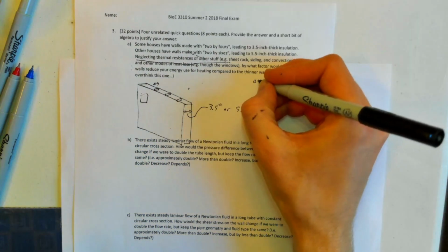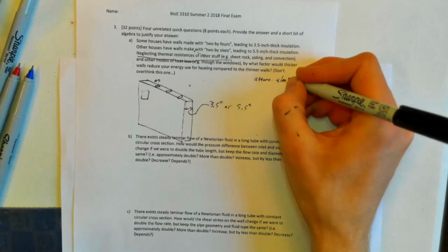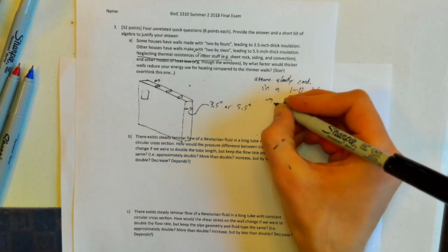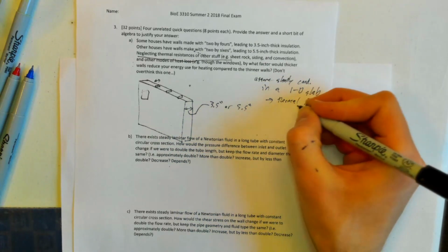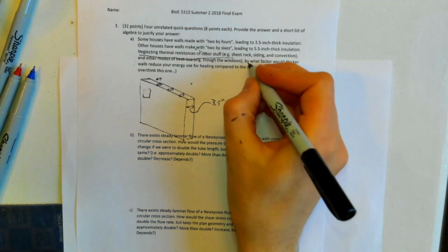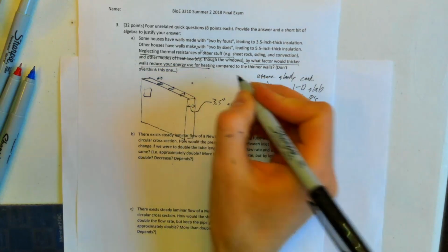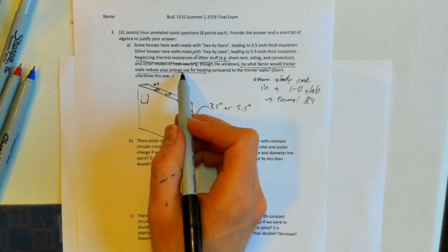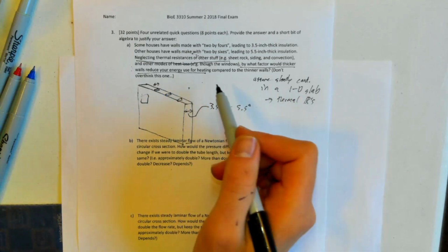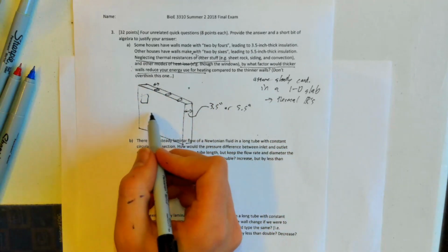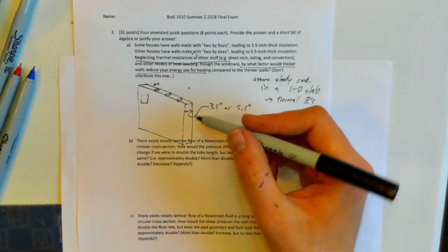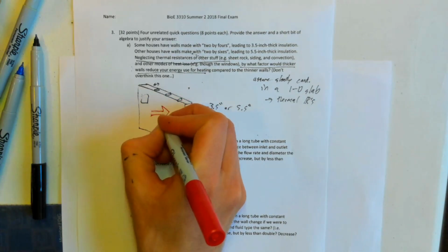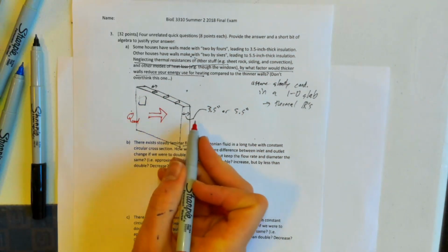So if we assume steady conduction in a 1D slab, we can use thermal resistances for this problem. They're saying, by what factor would the thicker walls reduce your energy use? If I'm thinking about energy use, energy use is essentially how many joules of fuel my furnace burns per month. Joules of fuel per month is essentially asking how many watts, or something equivalent to watts, flowing through this. So essentially, we're looking to investigate what is the Q conduction through this wall in either of these cases.